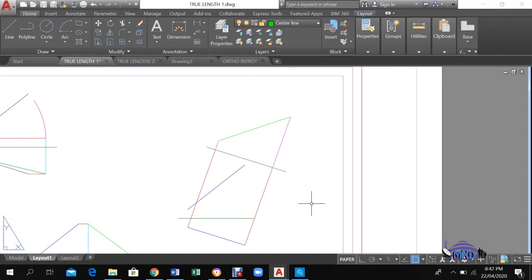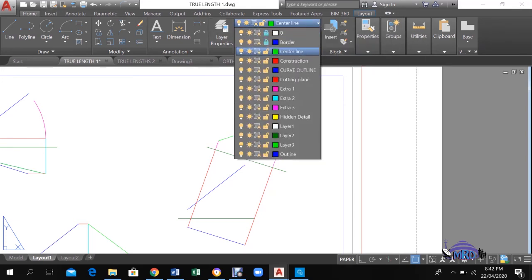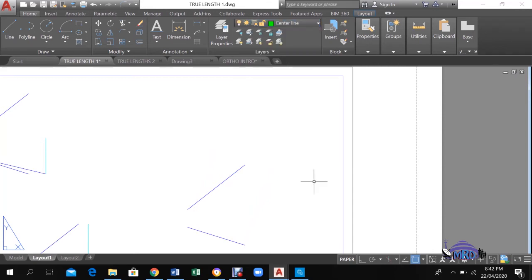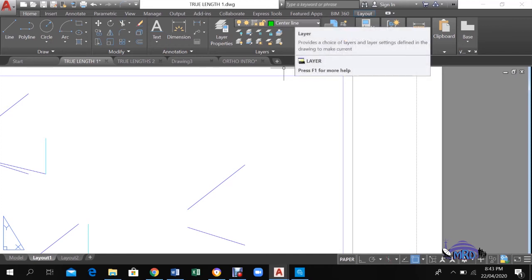get a true shape. So as per usual, let me take off a few lines so that we are able to move a little bit better. Okay, so now we have what we need to see. The two lines in position, front view and plan. And yes, I've deliberately left out the XY line. I will drop that back in fairly soon. The XY line will also be used in the transfer of the measurements for this one.